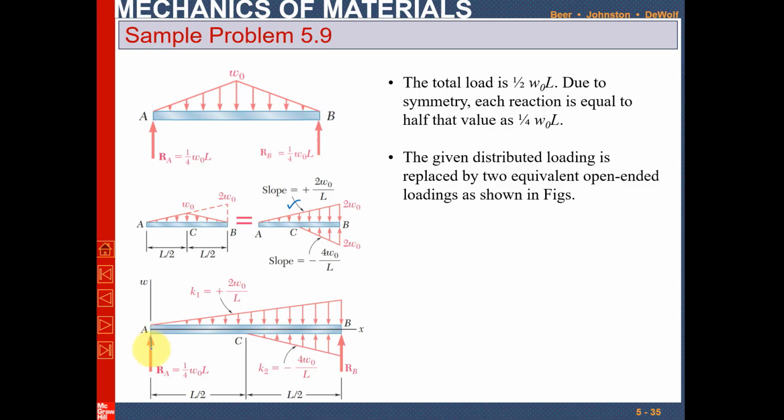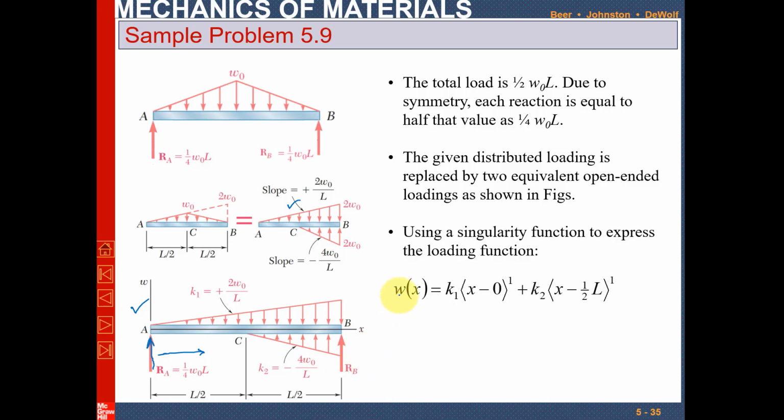Now the actual beam will have reaction forces at both ends as well, and the beam is transformed into a new type of loading. Always remember that we will take the reaction forces or any forces that are available on the left side, because we start drawing the sections, or we move, from the left side to the right side. So anything on the right side will be neglected.